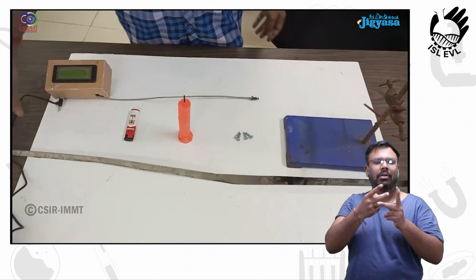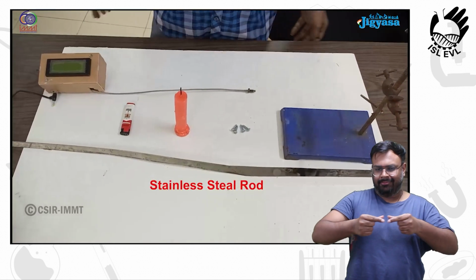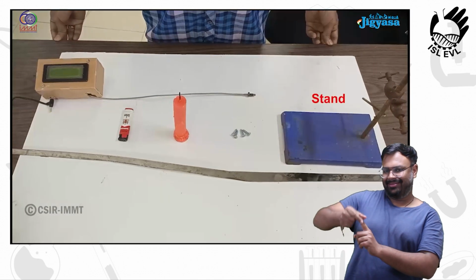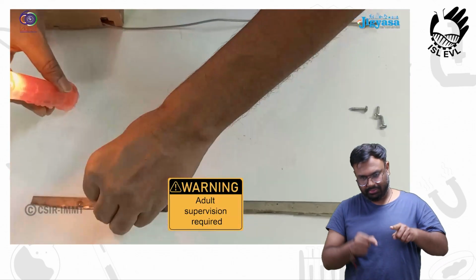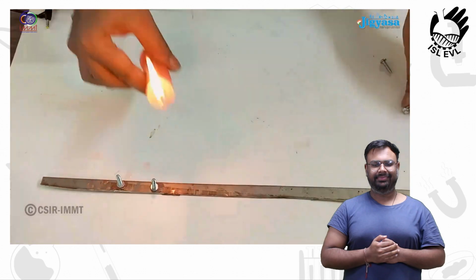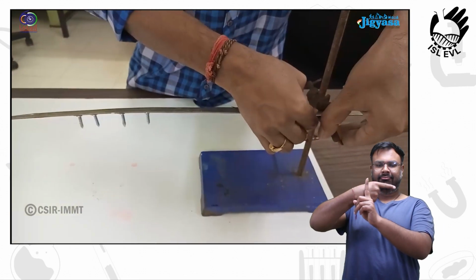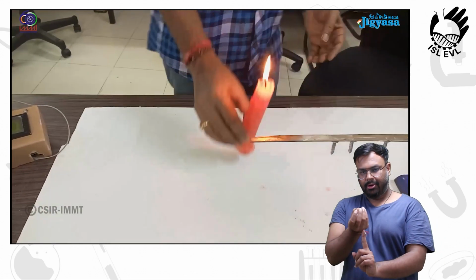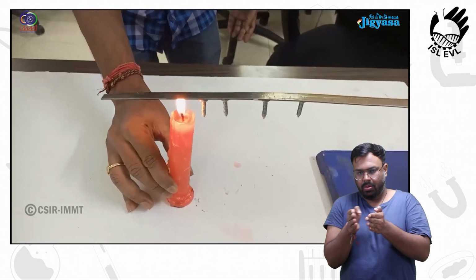To perform the experiment on conduction, we require a flat stainless steel rod, 4 nails, a candle, a stand, and a lighter. First we fix 4 nails on the flat stainless steel sheet by putting hot wax on it. Once they are fixed, the rod is clamped with the stand. Then the candle is lighted by the lighter and is placed below one of the ends of the rod that is slightly distant from the first nail.